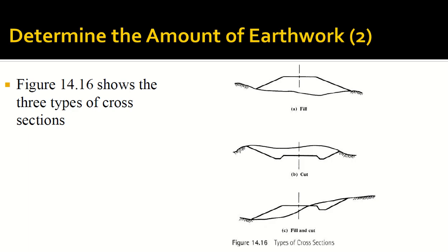This is called as embankment. Okay, now tell me which slope is more stable, the one which is steep or the one which is flat? Which one is more stable? Flat one is more stable, right? But flat one needs more height and more length. To make it flat, I need extra material fill here, right?